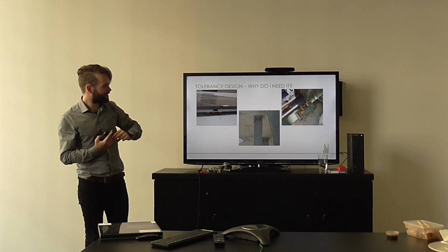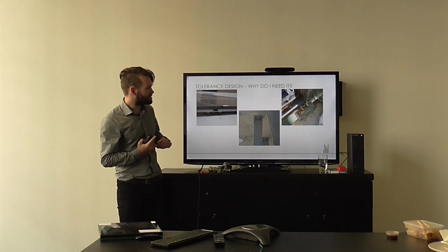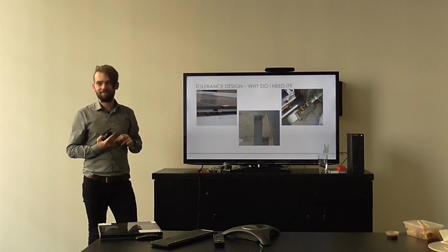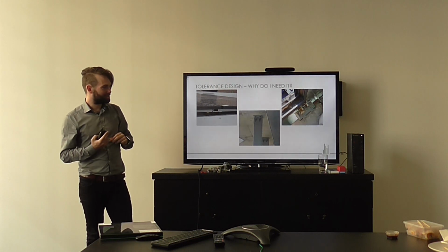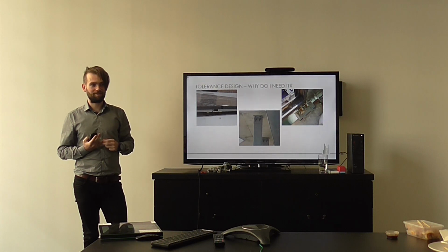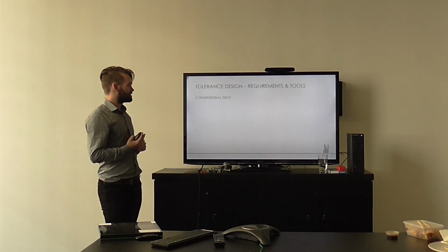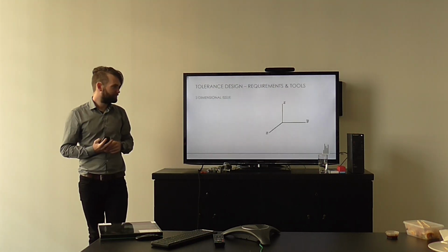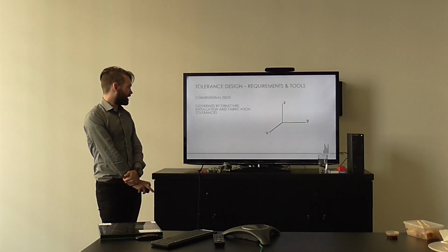The one at the top right is a situation where the bracket has missed what it's connecting to. From discussions with the members on that project, some pretty serious works needed to be done on site just to get that bracket supported. So essentially, tolerance is a three-dimensional issue. We need to think about it going in four ways.